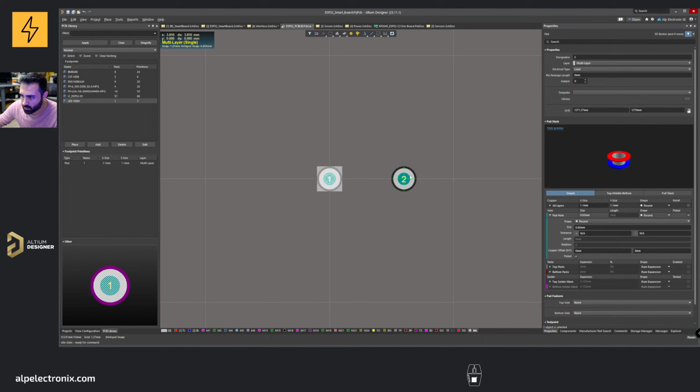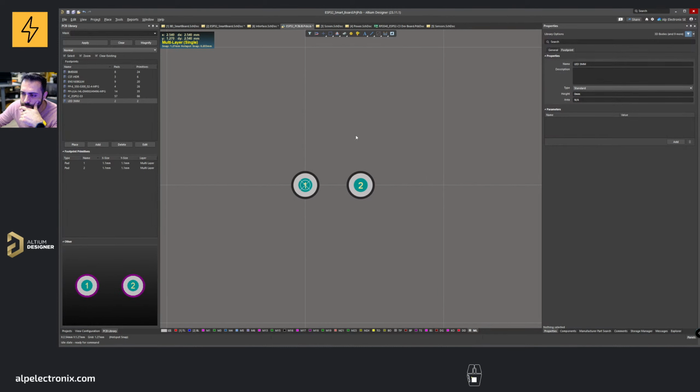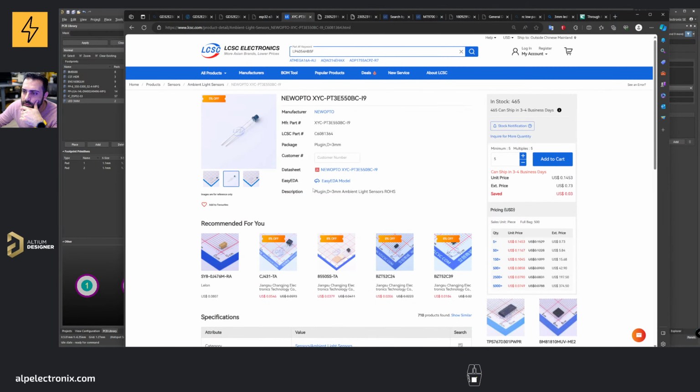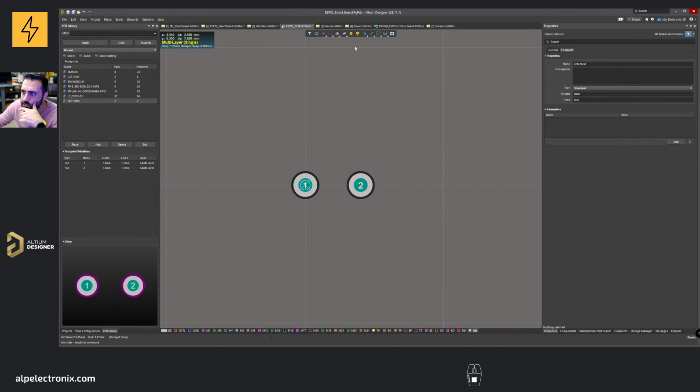Yes. And then you can actually watch the top left here. So it shows the distance, like this is 0, 0, and then it goes like 1.27, and then 2.54, and I just click and then place it here. And then we can do a little bit of cheating. This second pin says plus, and there is this top layer silkscreen, and then we can do the same basically.